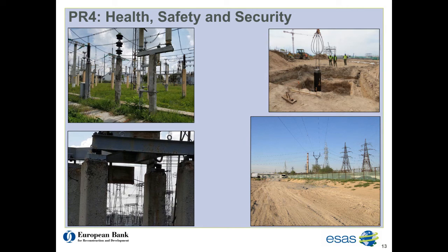The loads are not secured by qualified and competent riggers and slingers. And from the photo in the top right-hand corner, you can see that this heavy load is not being secured during the lift. Furthermore, wind and weather conditions are also not monitored during lifts. There is no maximum permissible wind speed.